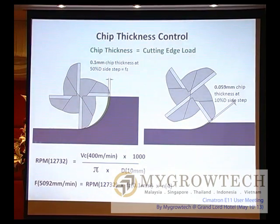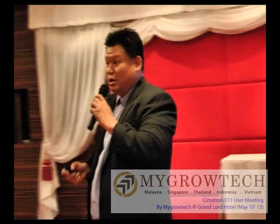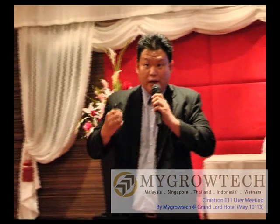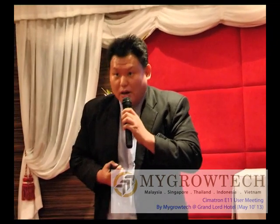So within the same RPM and feed rate, the difference is the side step. If 50% is 0.1, it is equal to FZ. But if this side step is 10% of the cutter diameter, it is now 0.059. The chip thickness actually reduced a lot.